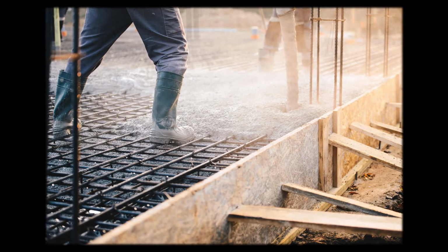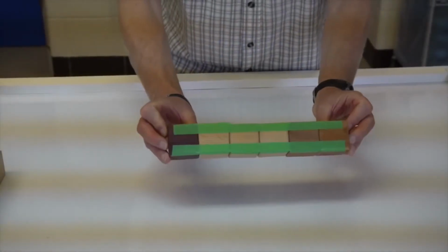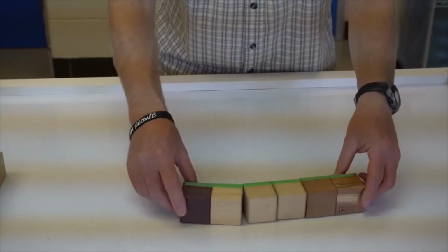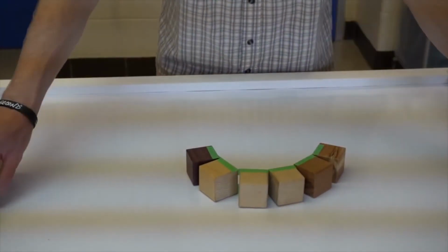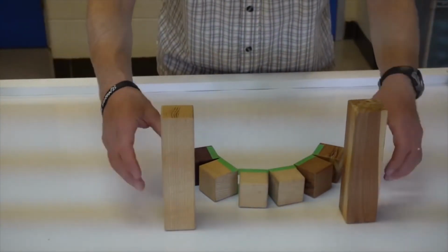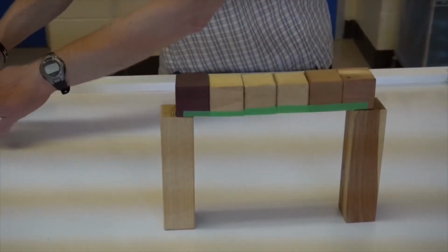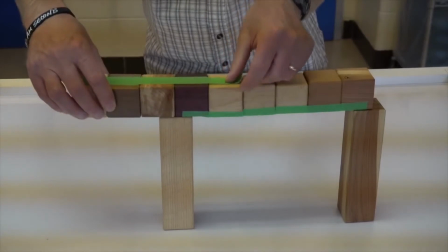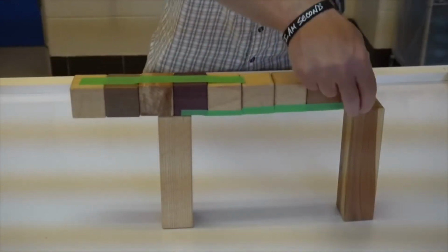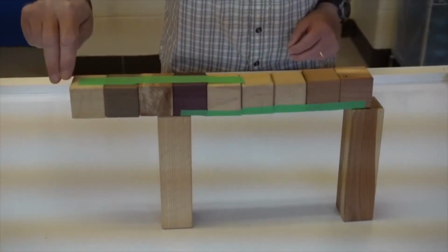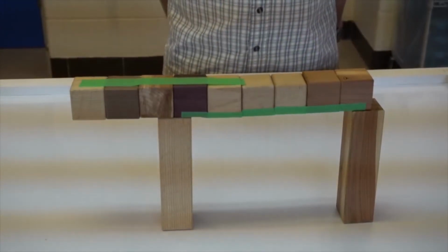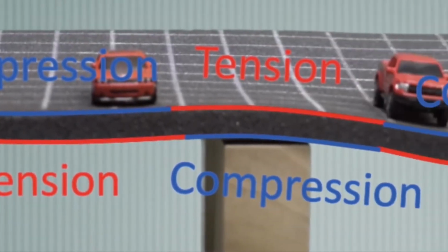Understanding plate curvature is especially important in the design of concrete floor slabs. The reason is that concrete, like the blocks in this model, cannot be relied on to carry tension. Consequently, steel reinforcing must be incorporated any place that tension could arise, and that includes the tension side of any regions where bending occurs. That is why it is important to know the direction and the degree of bending at every point in a plate.